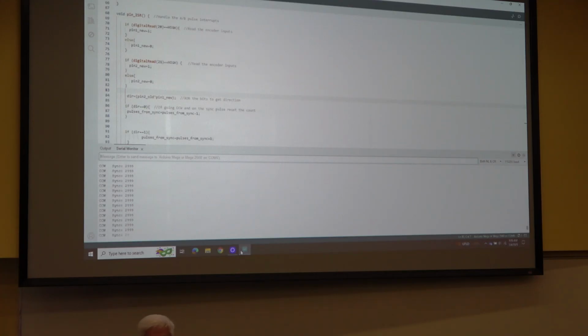I know something's wrong. I'm out of range. This is a 100 pulse per rev encoder. So if it's saying 3,000, I know I'm bad. But as I rotate this thing, so I'm rotating it clockwise, my numbers are increasing right up until the flat is on the top, or the cables come out on this one.